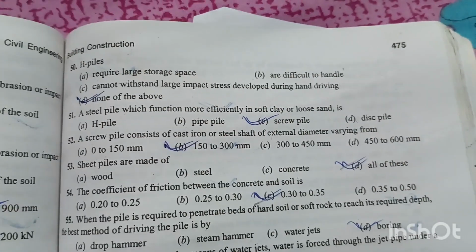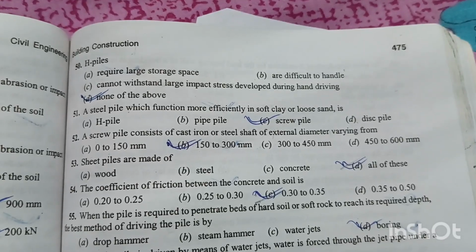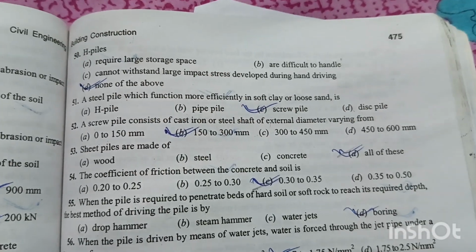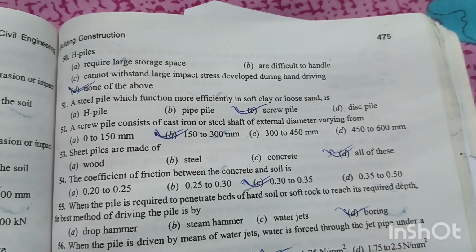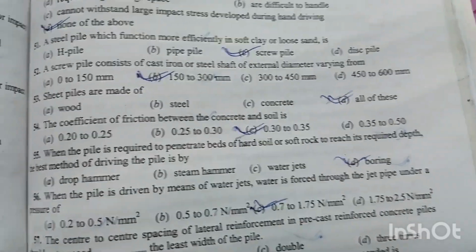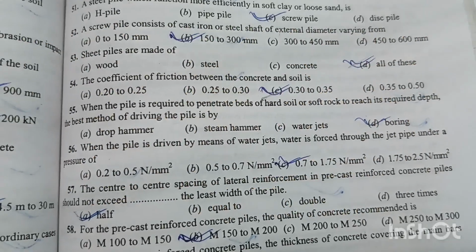A steel pipe which functions more efficiently in soft clay or loose sand is screw pile. Option C is the right answer. Question number 52. A screw pile consists of cast iron or steel shaft of external diameter varying from 150 to 300 mm. Option B is the right answer. Question number 53. Sheet piles are made of wood, steel, concrete. Option D is the right answer, all of these.